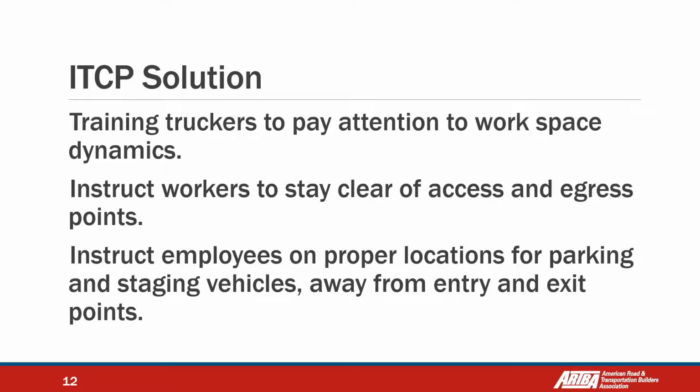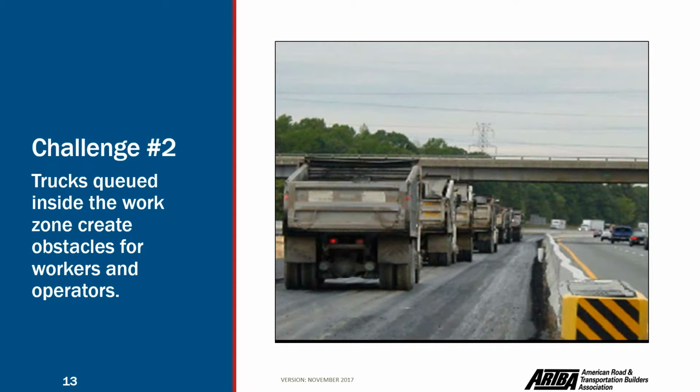But sometimes they just arrive at the access zone and leave the vehicle there, and they are not thinking about the traffic that is waiting in the area, for dump trucks, for example. So the parking zone should be far away from the access zone, or a special area that doesn't create a problem for vehicles arriving to the work zone.